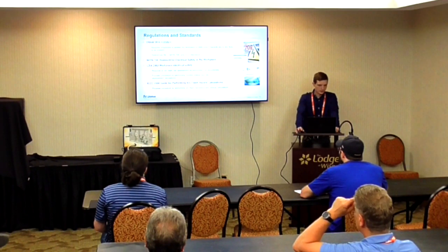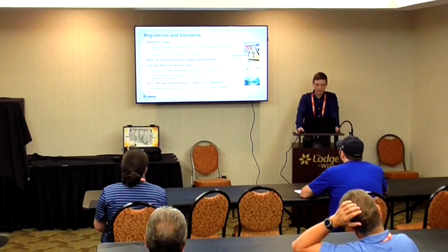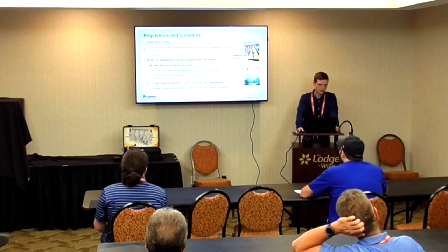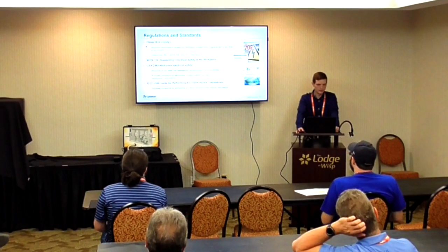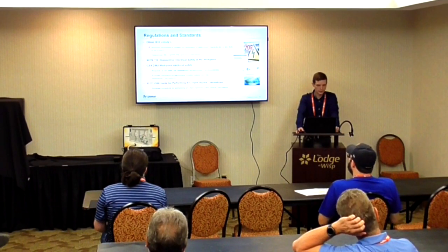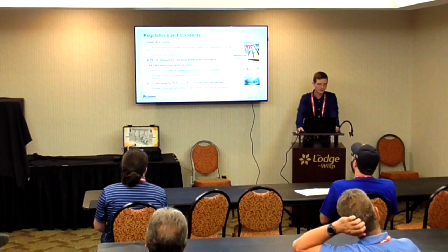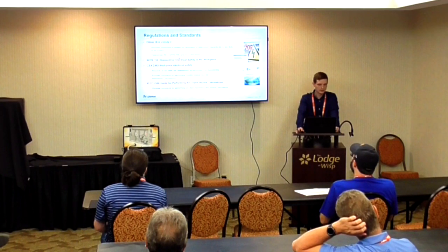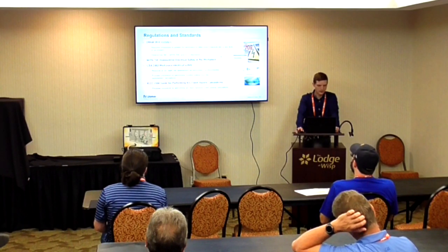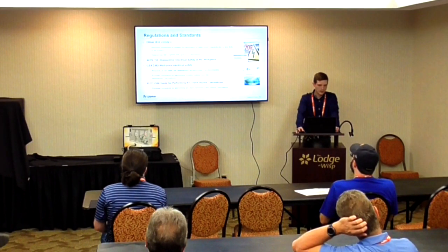All right, some of the aforementioned regulations and standards. I'm sure everybody here is familiar with OSHA. OSHA, specifically 1910.132, is the required protocols for arc flash. This is based on guidance from the NEC, the NFPA 70E, and the IEEE standards. Speaking of the NFPA 70E, this is also one of your guiding regulation bodies. I do have CSA on here. I know most of you aren't worried about that since that's primarily a Canadian thing.